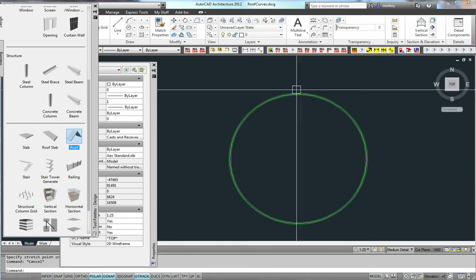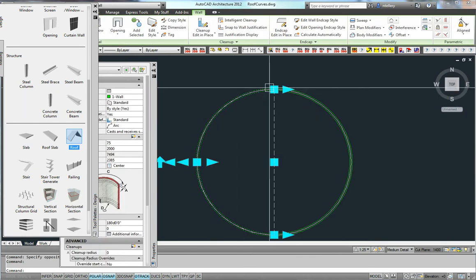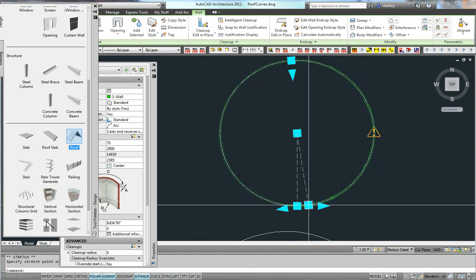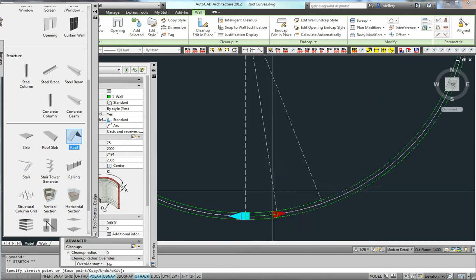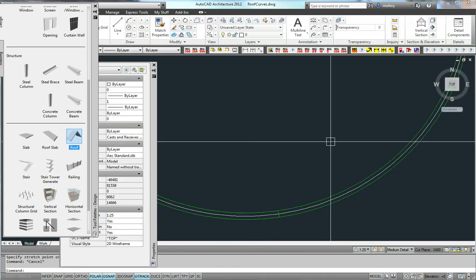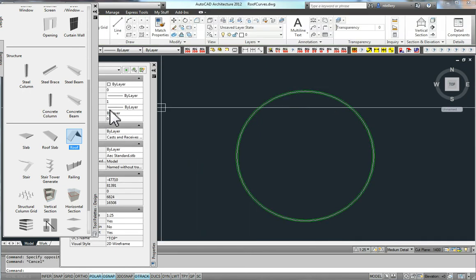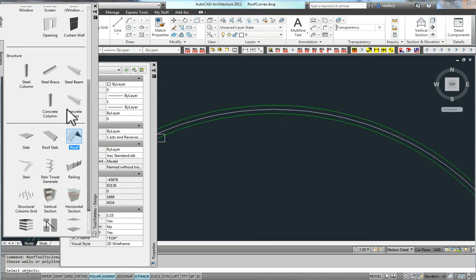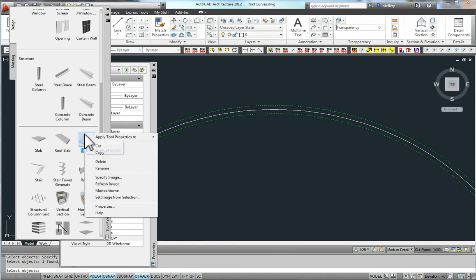If you're doing your elevations and you want to get rid of the lines, you can probably, for the most part, squeeze that around to somewhere, maybe back behind, where that's not going to be so noticeable. But for now, for creating the roof object, it's probably best that it's just two equal arcs. So I'm going to apply it from the palette, and that's the only place where you can actually apply to line work or to walls. So you get this right click option.